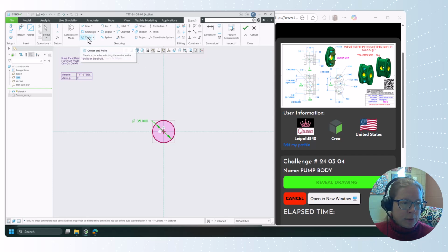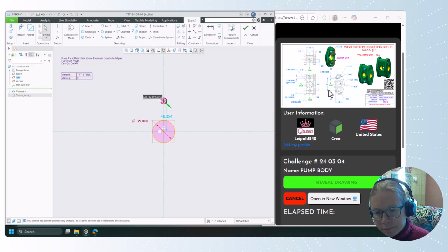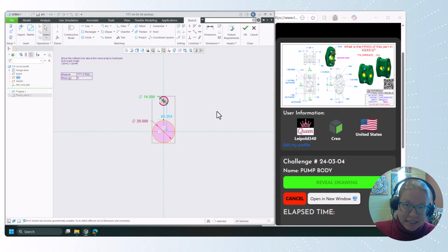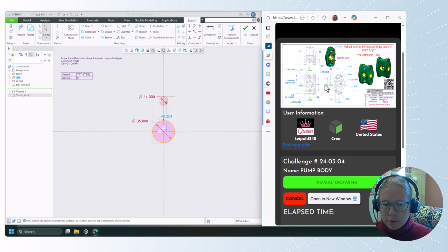And I've got another one up here above it. And that has a diameter of 14, I'm pretty sure. Right here is where we see it on the side view, which again is a hidden line. It's not in the view I'm looking for it. I'd like that to be shown a little bit clearer. It's also a little challenging to understand exactly who gets the 90 and who gets the 92. So let's see if we can zoom in here.